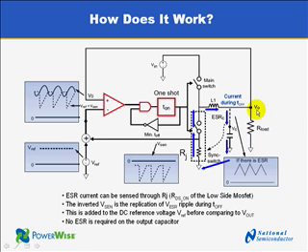Now let's look at the voltage regulation. The output voltage is sensed and fed back to the comparator and compared with the internal reference. The sinusoidal waveform here is coming from the fact that the output capacitor has no ESR in series. This is not causing a stability problem because the signal is not compared with a DC reference, but with a DC reference plus the ripple voltage across the RDS(on) of the MOSFET.